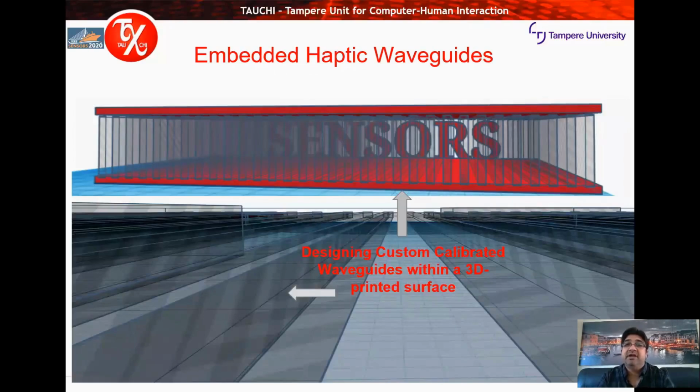With this in mind, we created multiple waveguides within the 3D printed object by designing a 1.5 millimeter wide chamber or shaft-like indentation inside the surface itself, with a ratio of solid waveguides to empty space of 1:1. Here, the solid material acts as a waveguide, while the empty space provides an insulation around the waveguide, reducing the unwanted propagation of the applied signal. This technique reduces unnecessary energy dissipation and guides the applied signal from the actuation source to the point of contact.